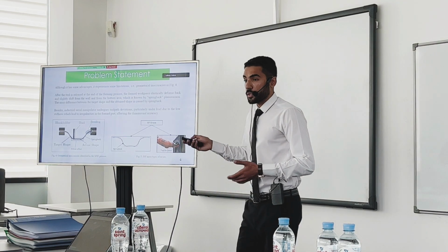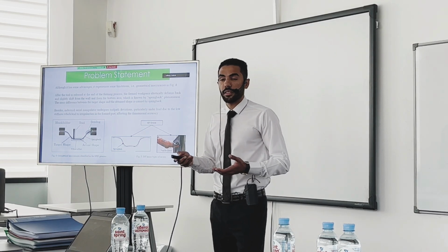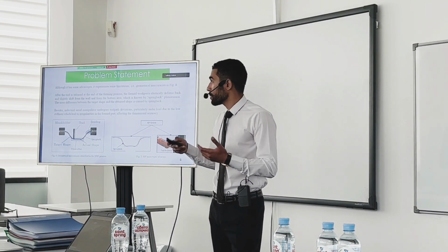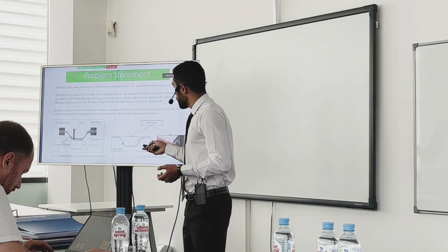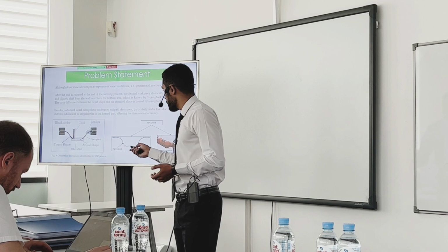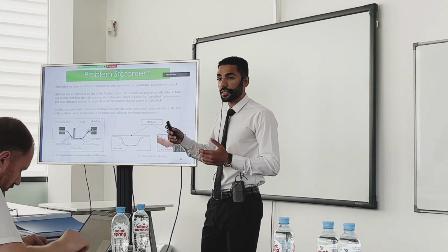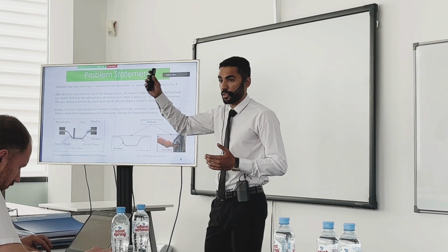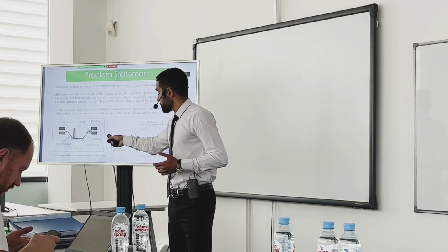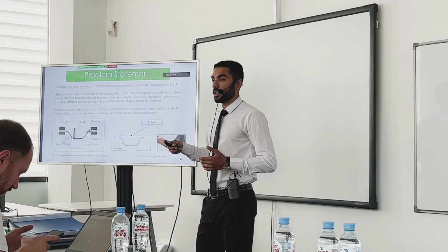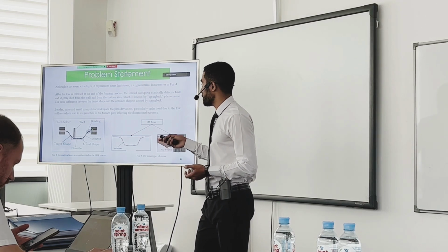Okay. Although this process has a lot of advantages, it experiences some limitations, which are basically the irregularities and geometrical inaccuracies, which are presented in figure 4. So the base of the sheet suffers from a pillow effect, which is the tendency of the base to counteract towards the center, and there's also bending at the clamped edge, and also the spring back effect, which is the critical disadvantage in this process.